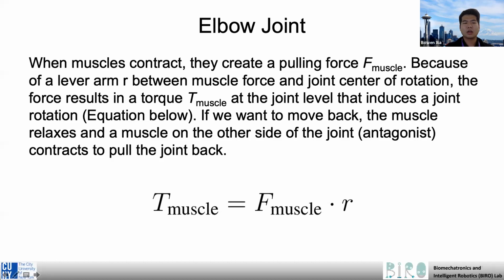So from this equation, we can know the force and the torque. We can get this force, and we can measure the R, which is the length of the arm, and then we can get the torque. With this torque, we know how to apply it to our servo motor. When we are writing the code to control it, it might be very important. And that could be another safety measure so that we don't hurt ourselves when doing this test.